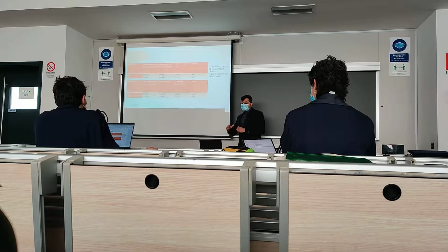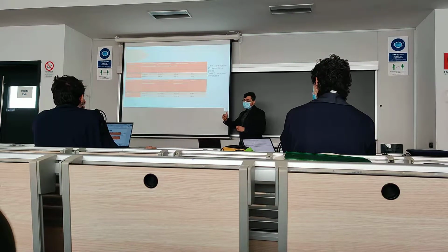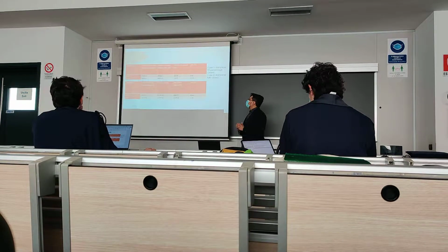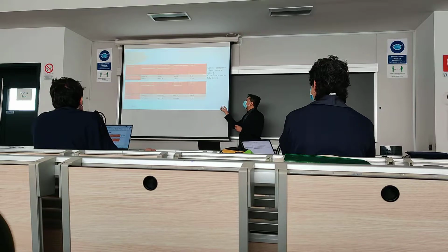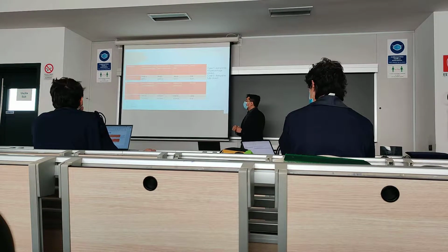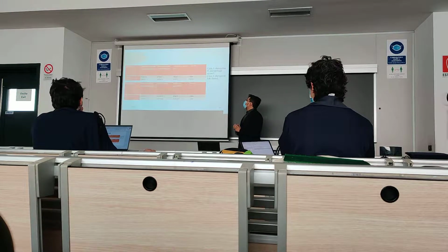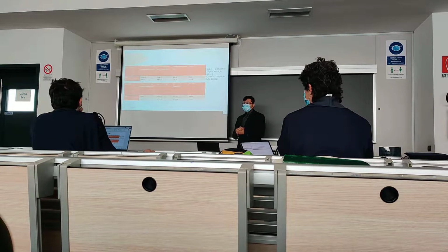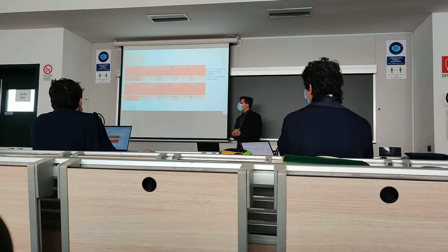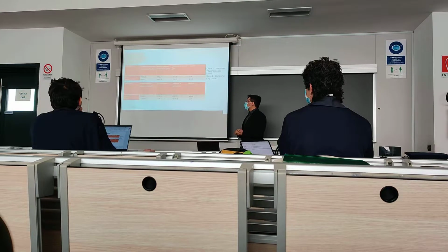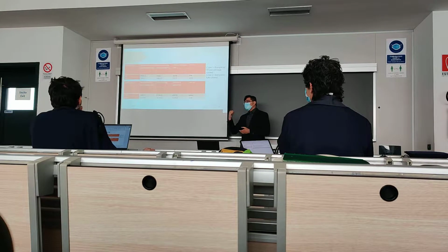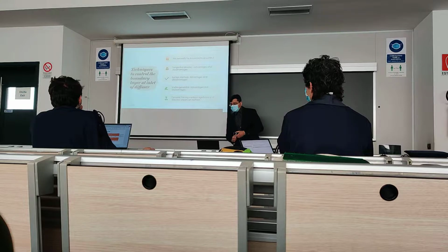What we obtained was that the LabVIEW software static reading was different from the pressure measuring device reading, but the error was very small, like 0.46 and 0.119, which was okay. But when considering case 2, when the damper was fully closed, at the maximum pressurized zone, the error percentages were significant, as you can see, 6.8% and 12.9%. This was repeated for both the static transducer and also the total transducer.